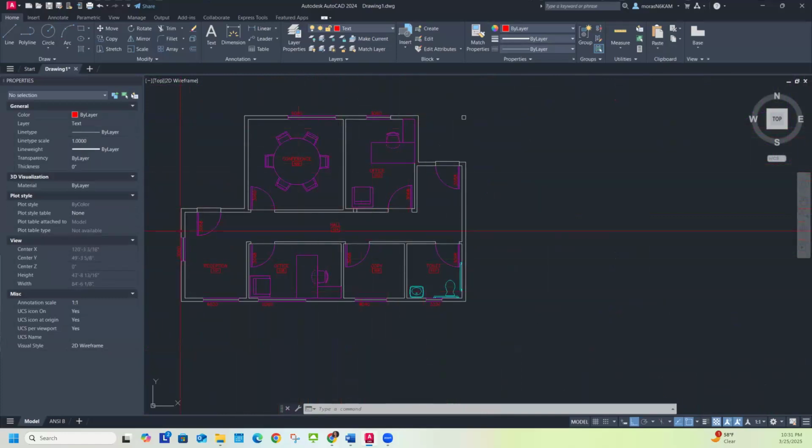Okay, so I have all my windows and my doors labeled. Okay, and so now I just need to dimension. And so when it comes to the architectural dimensioning, I want to start off with the overall building dimensions and then the exterior shape and then the interior walls, and then dimension to the doors and the windows. But I'm not going to actually dimension the doors and the windows because I have the notes that specify the size of them.